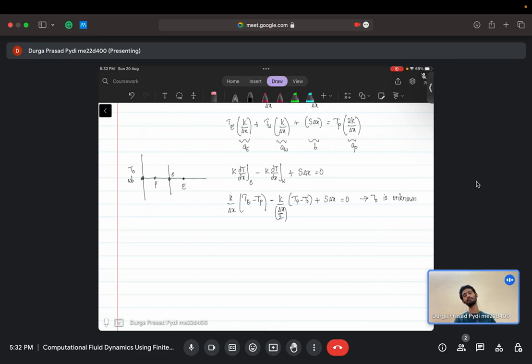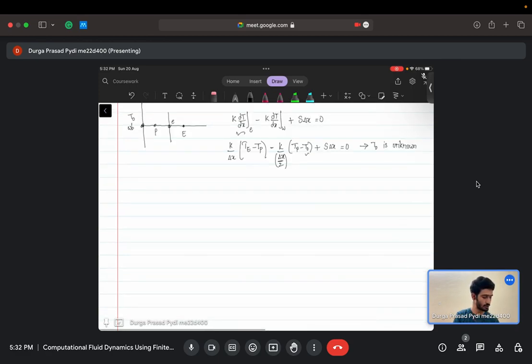Previously, when we were dealing with Dirichlet boundary conditions or Neumann type conditions, in Neumann type conditions the entire flux value is given, so you directly substitute that value and wouldn't have an unknown there. When you have a Dirichlet condition, T0 is a known value, so you don't have to solve for it. But in this type of boundary condition, T0 is an unknown, so you need to replace it with some known value. Now we will take the boundary condition to see how that happens.